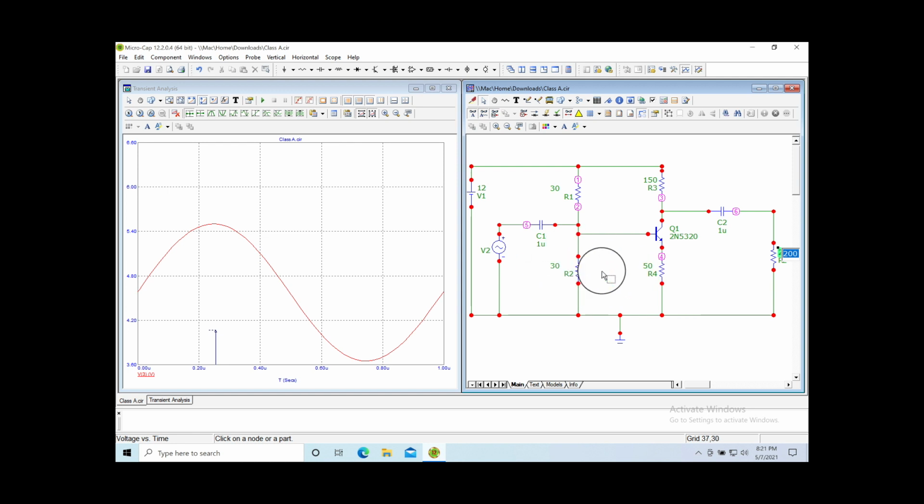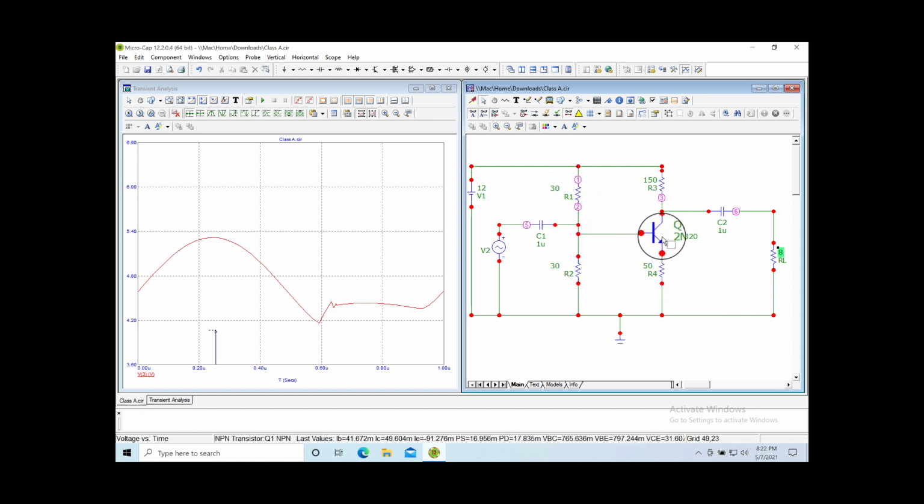Let's drop that load. Now that we've dropped value, you remember this guy was in parallel with this and all that, and plus we didn't have a transistor big enough. Let's drop this back down to 80 ohms. Hardly even affected our output. Okay, let's get brave and make it 8 ohms. It's kind of crashing again. All right, we have plenty of drive, I think, and this transistor can handle the current. I think the problem is 8 ohms compared to 50 ohms over here.